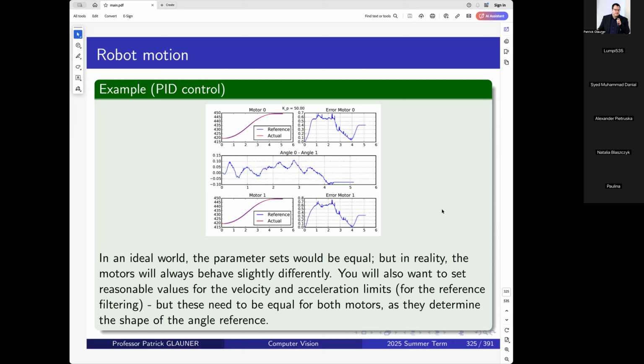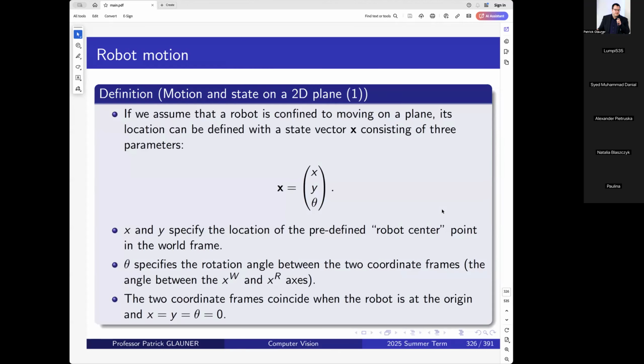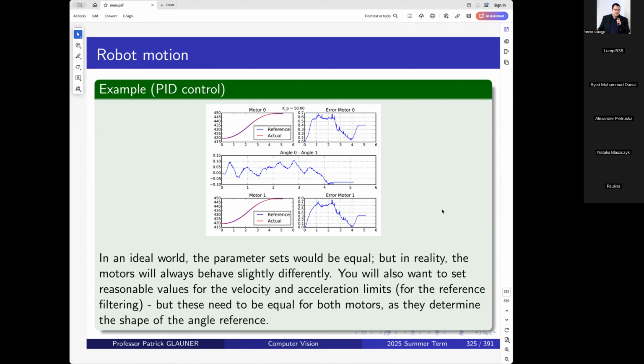This is something that I've done a few times on my own. Maybe it's something you also need to explore in a lab if you notice that your robot doesn't drive straight. But there are lots of other reasons why your robot may not drive straight. Maybe one of the wheels is not mounted on properly. So check that the wheels are mounted properly. Otherwise, you just do lots of unnecessary work with a PID controller here. Better make sure the wheels are mounted correctly.